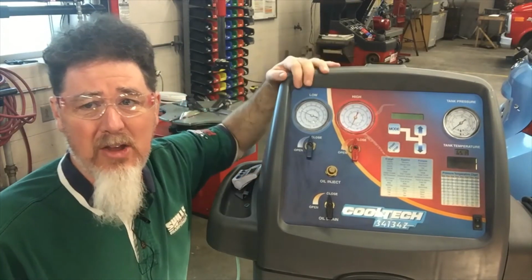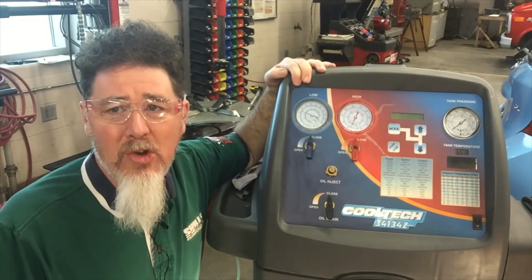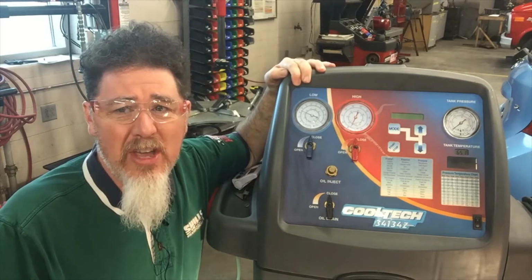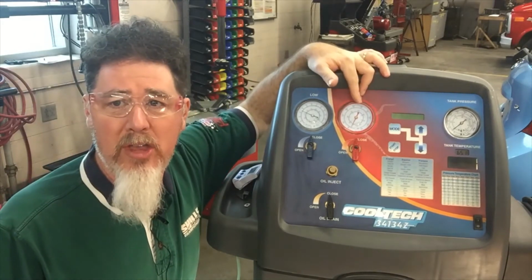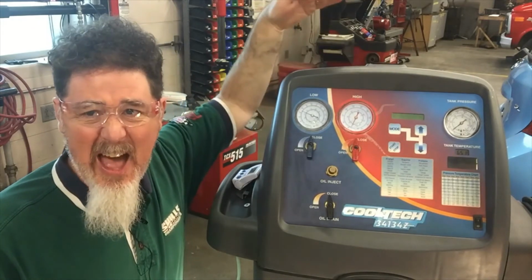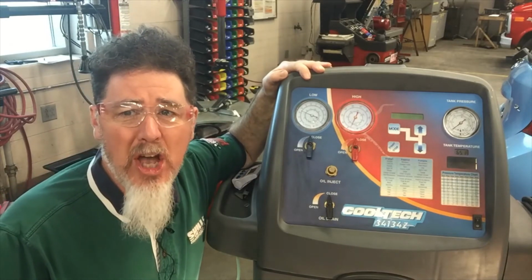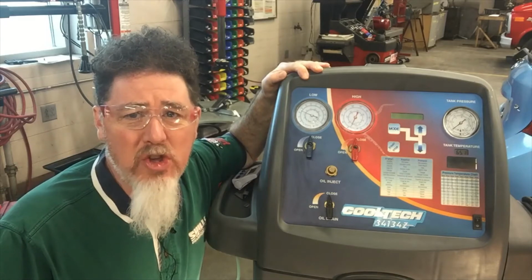The high side and low side service ports are connected together through the pressure drop of the normal TXV system. So again, this is much harder to find. If the high side service port was on the discharge line before the restriction, we would expect to see higher pressures than normal because of this particular problem. Let's turn off the vehicle now, and let's see what happens with our equalization time.